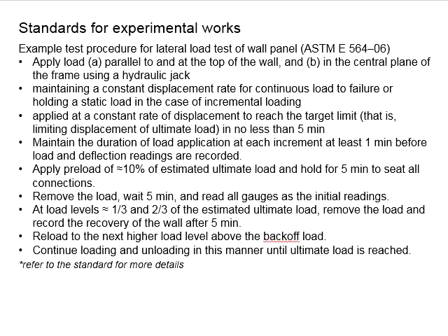Or if you use the static load incremental approach, you will need to maintain the duration of load applied to each increment at least 1 minute before the displacement readings are recorded. That means if you use the approach where you increase the load stage by stage, you will need to maintain the load for at least 1 minute to allow the stress to be properly distributed within the element before the displacement readings are recorded.